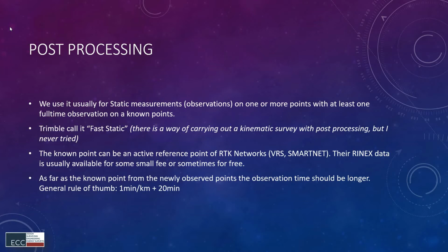The very important thing is that everything will be measured on the same day. So you can't measure 3 hours on the base, then shut down, and then do your rover points. Everything is time specific. It has to be simultaneous, at the same time. Otherwise the vectors, the baselines, they just won't work.